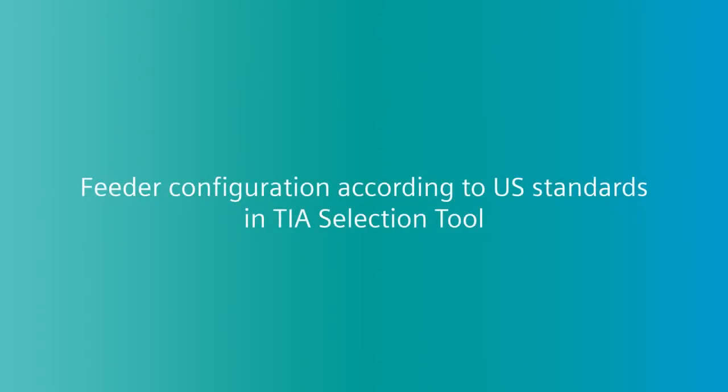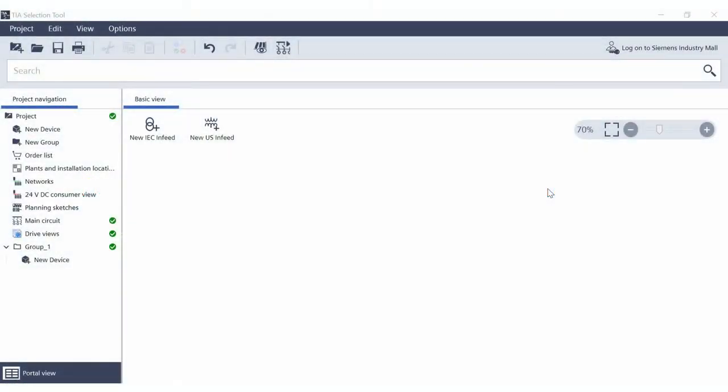Feeder configuration according to US standards in TIA Selection Tool. Control panel design in TIA Selection Tool now supports the design of load feeders according to North American standards. You can now see how this works directly in TIA Selection Tool.